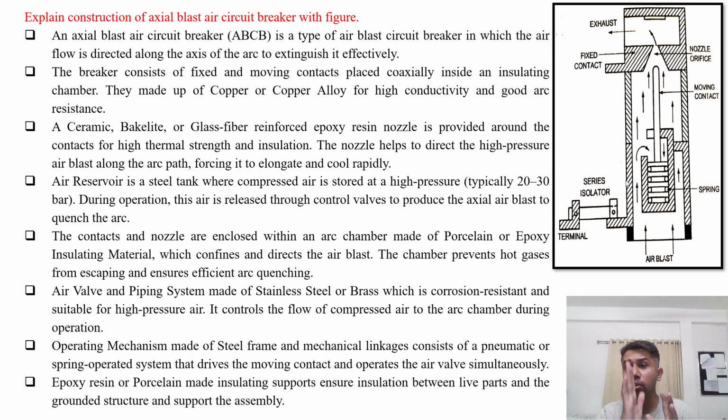So the airflow in the breaker increases rapidly so that the arc can be quenched quickly. Epoxy resin or porcelain insulating supports are provided, which ensure the insulation between the live parts and the grounded structure, and they support the assembly. Here you can visualize this. The series isolator is also provided here for the proper result. This we are going to explain during the working of the